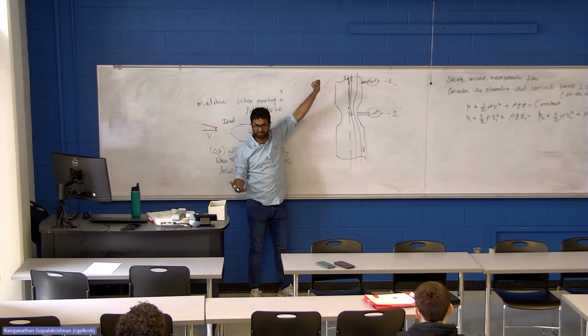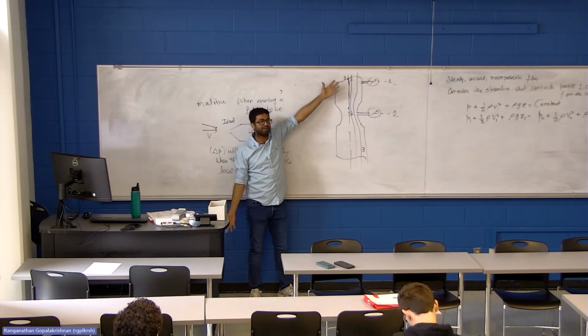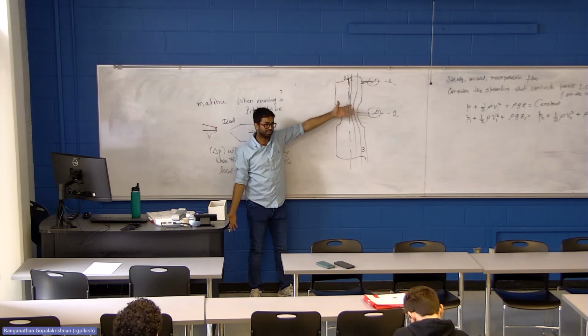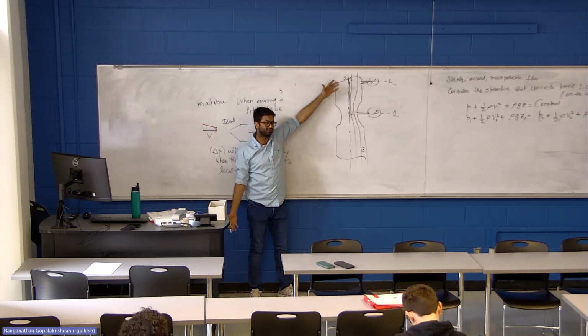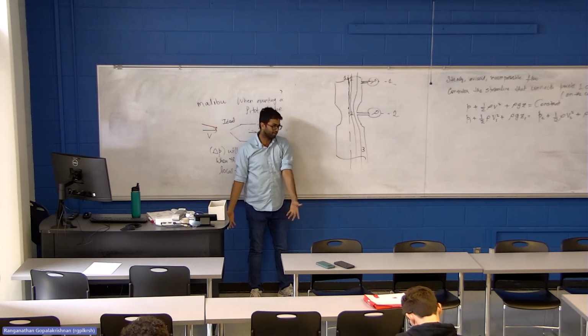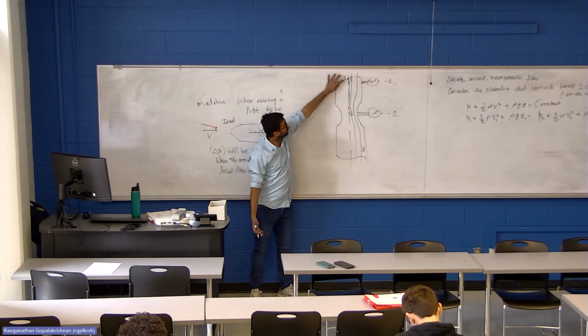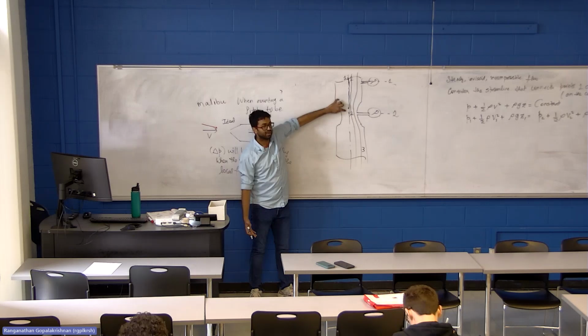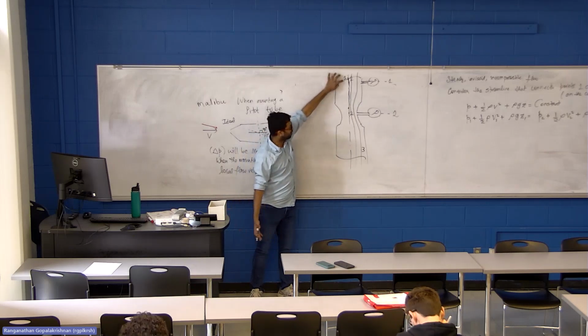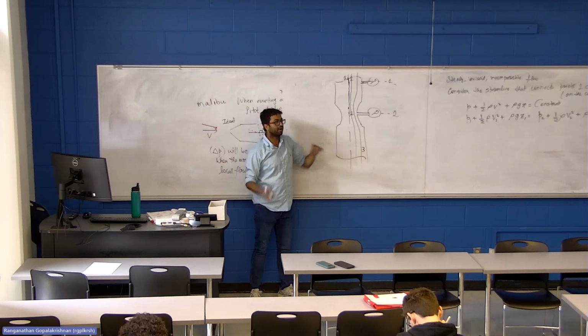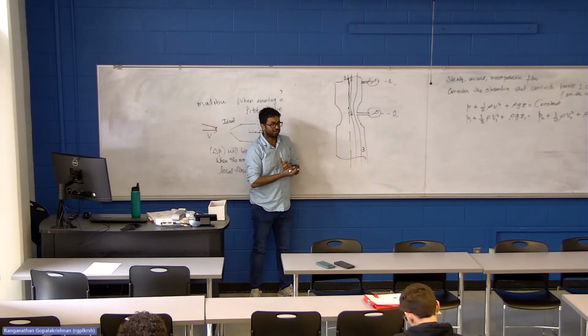You can't jump streamlines. What I meant by Minneapolis is the river Mississippi. It starts near Minneapolis and flows down to St. Louis, Memphis, and New Orleans. You know this. So you can apply it between 2 points connected by the same streamline, but you can't apply it between points not connected by the same streamline. You can't jump across streamlines.